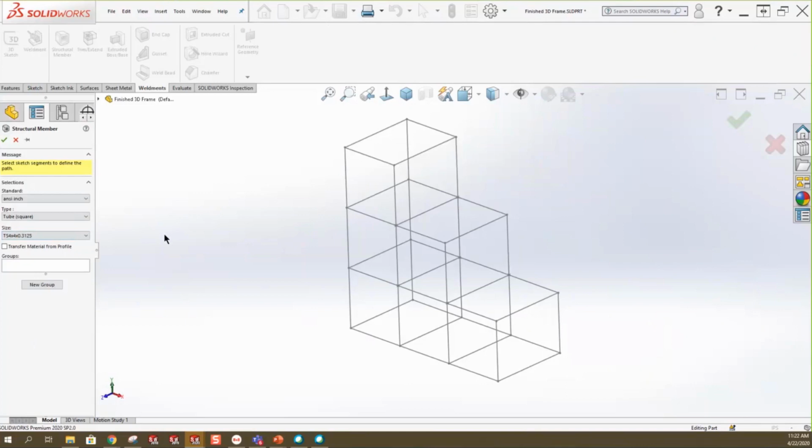And what's really cool about dealing with weldments is, I'm sure you guys have run into this. I'm trying to design an extrude, and I've got all these construction lines to help me get the shape going or whatever it might be. In weldments, it doesn't care. I could have lines, I could have points, I could have circles, I could have all sorts of stuff that I may be using for reference that I'll never select, and it will not hurt because I'm not trying to use this sketch to actually extrude a physical being. I'm not taking this outside border and trying to extrude an L, right? I'm just trying to use this as a frame.